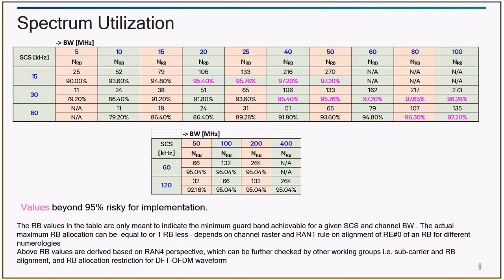But when you do a power sweep, you can identify approximately if the network is transmitting, let's take 100 megahertz, then you see the energy only in that 100 megahertz. This is how even the LTE band scan happens today. But initially, you don't know about the bandwidth of the signal. It's not 100% accurate. There are GSCN frequencies which are defined, the global sync channel number. It works very well at a good channel, but when you are at the noise floor, then you don't know where the boundaries are. Then it's very difficult to find.